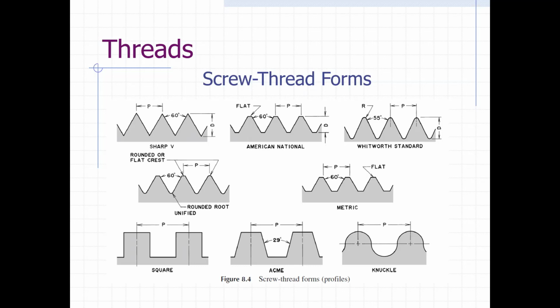Does that make sense? So you might not be able to actually model that particular thread in there, but in the drawing it's just going to be a series of hidden lines and solid lines that represent the threads. It's a symbol for threads, so it doesn't have to be the exact same shape. You just put the note on there right.